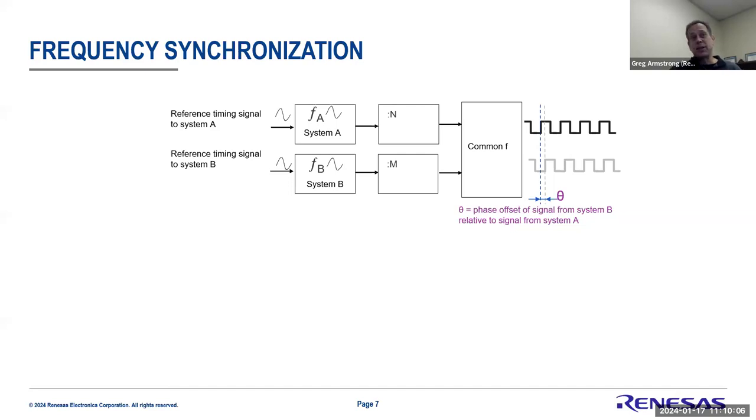So frequency synchronization, much as the term says, is looking purely at the clock. If you're looking at it from multiple clock signals, and you divided those clocks down to a common frequency, like I mentioned, 8 kilohertz or even 1 pulse per second, and looked at the relationship of edges of that common clock, you would see a phase offset between them, but it would be a static phase offset.